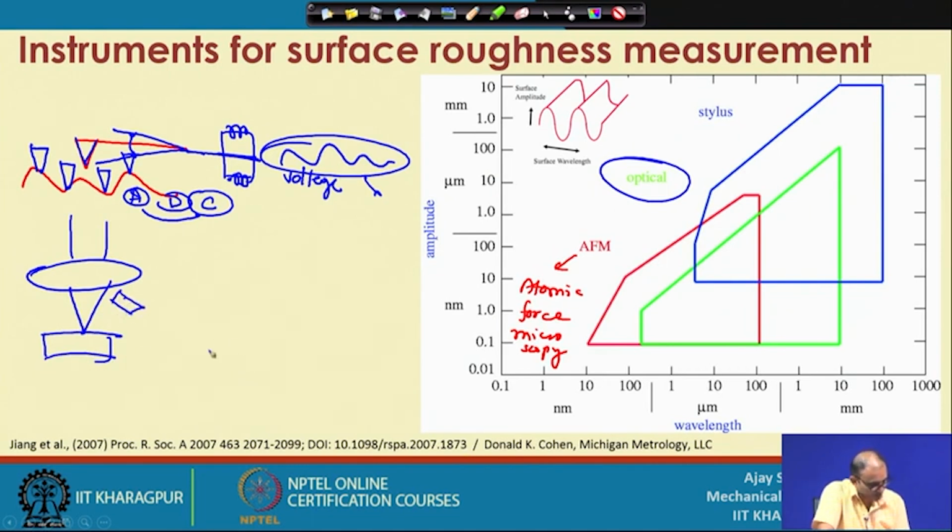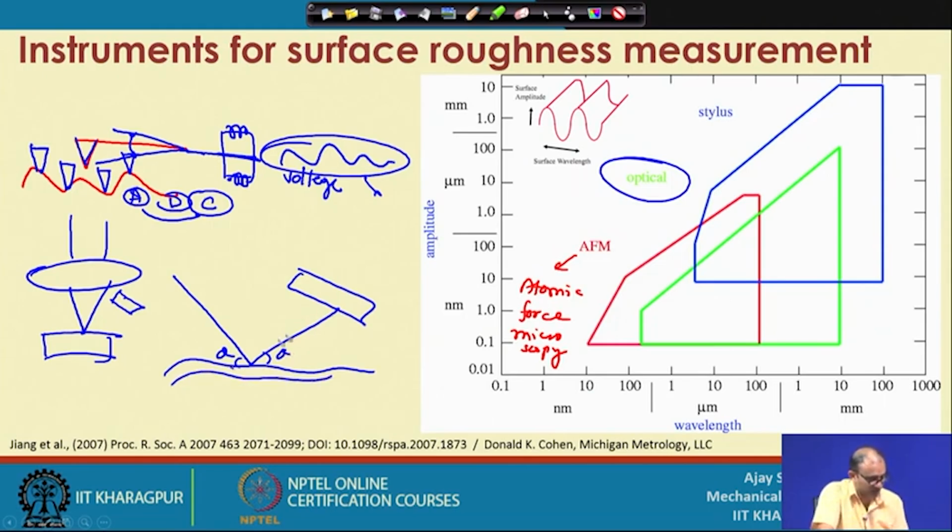So, what is going to happen is that suppose you have waviness, and light is passing here, and then you have one particular receiver. When you have a flat surface, this angle and these angles are the same, and if you have waviness here, then these angles are different. So this particular location will be different at different locations, and this way you can optically measure the roughness.